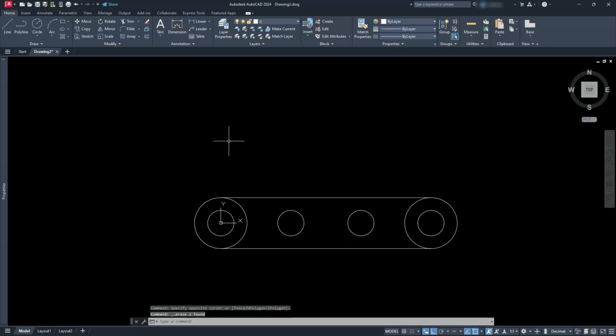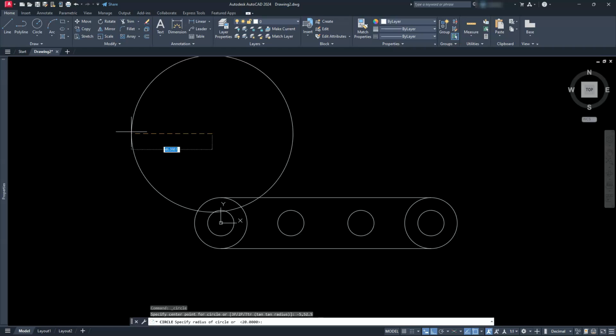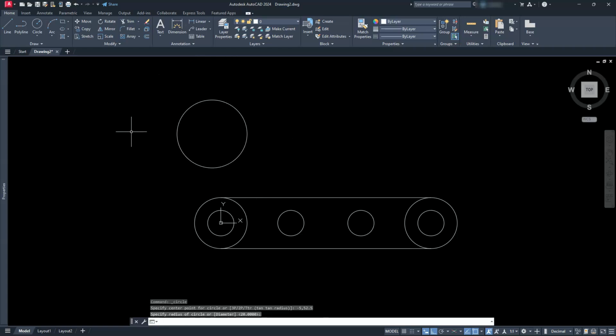I'm just going to delete this. I'll go back to circle, center radius. And I got to make sure I hit the negative button. So -5, comma 52.5. So 52.5. Go ahead and hit enter. And then this one has that radius of 20. So you can just type in 20, or since it was the last command I did.